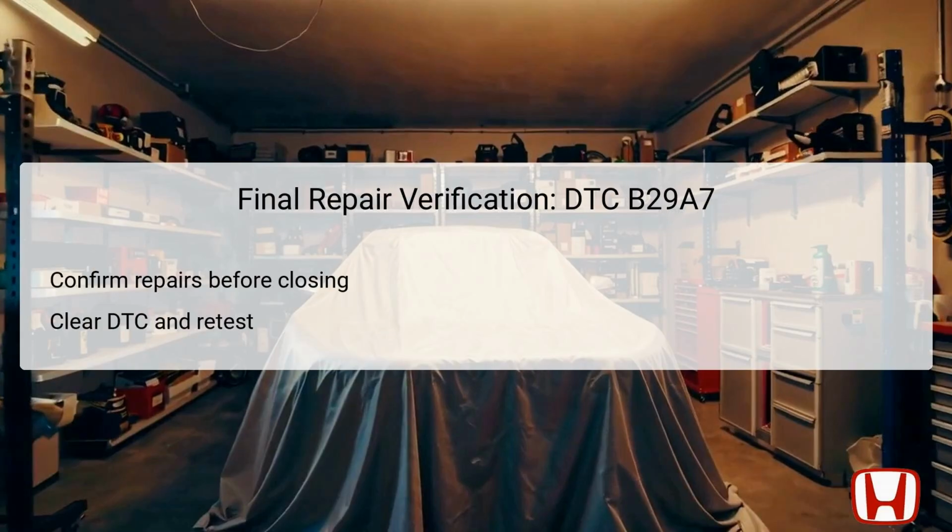After completing the diagnostic and repair process for DTC B29A7, it is essential to conduct final repair verification to ensure everything operates as intended. Start by confirming that all repairs have been done correctly, which includes checking all connections and ensuring that the replaced or repaired components perform as expected.